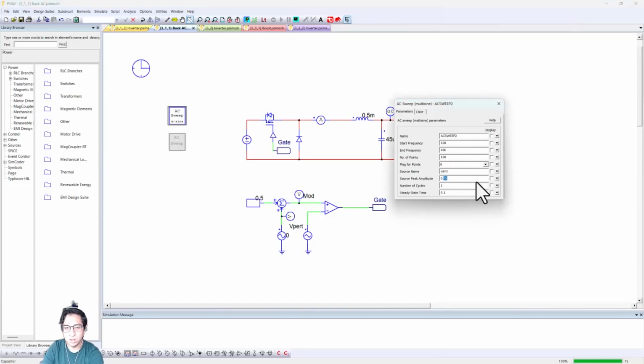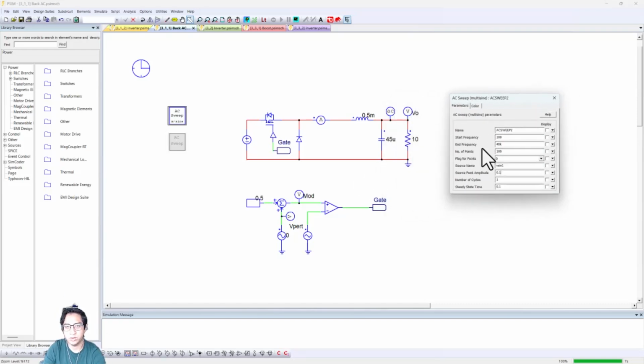We can place as much amplitude as we want, but we need to be cognizant of what we would be doing to the converter, right? If I were to put something higher, like 0.5 for the amplitude, I'm going to be putting a negative value here eventually, or the current can be super low and we will put this converter in another mode of operation. So we need to be very cognizant of what would be happening to the converter if we were to place these values. But for now, let's see if this higher amplitude will actually do us any favor.